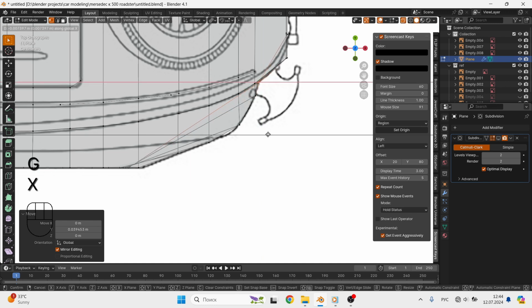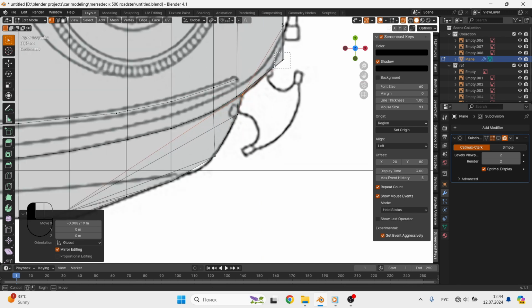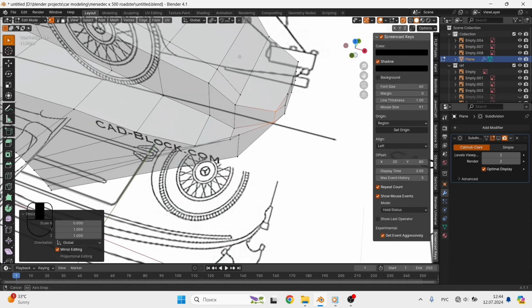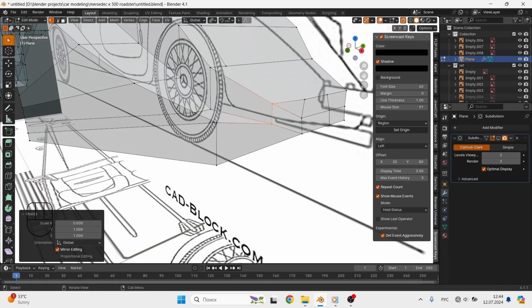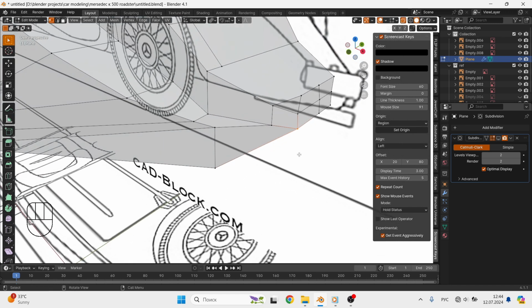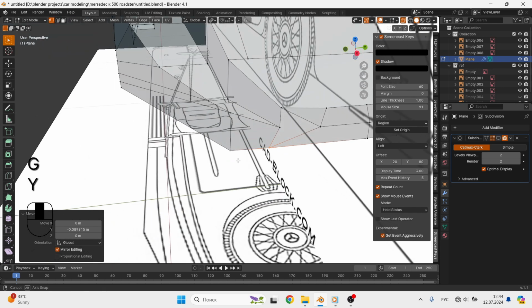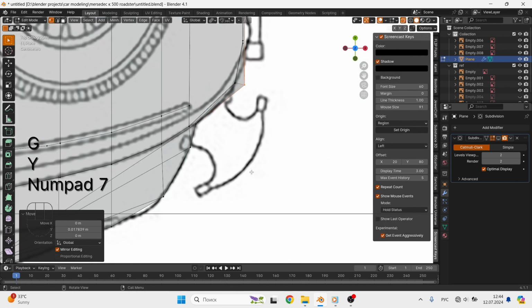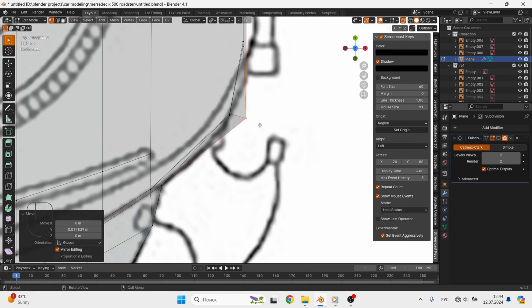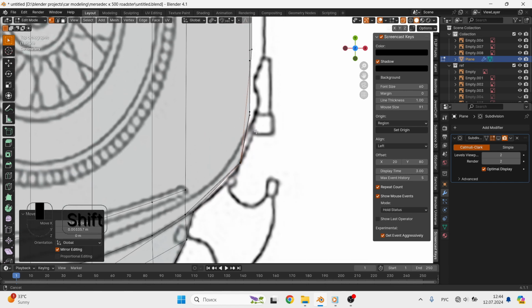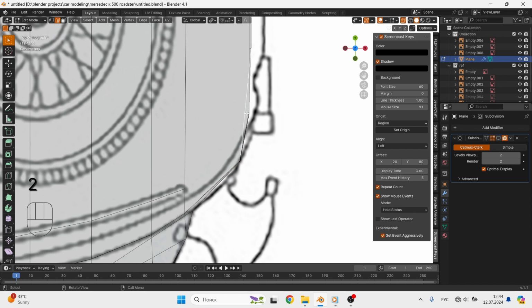It avoids the need to save and maintain huge amounts of data, and gives a smooth organic look to the object. The Subdivision Surface modifier does not allow you to edit the new subdivided geometry without applying it, but the Multi-Resolution modifier does. As with any modifier, the order of execution, the position in the modifier stack, has an important bearing on the results. Keep in mind that this is a different operation than its companion, smooth shading.